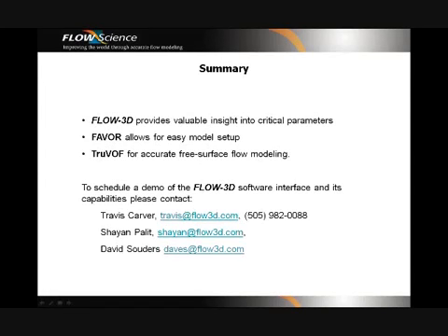Here's another question. Does Flow3D have mesh adaptation capacity? Well, our meshing is probably different than what most people are used to. Ours is what we call grid independence, so somebody can overlay a mesh on top of their geometry, and it's a fixed mesh where we break cells into area and volume fractions. One thing we can do is carry it a little further by adding multi-block to set regions of higher resolution in areas that are of interest. But the mesh does not change dynamically with time.